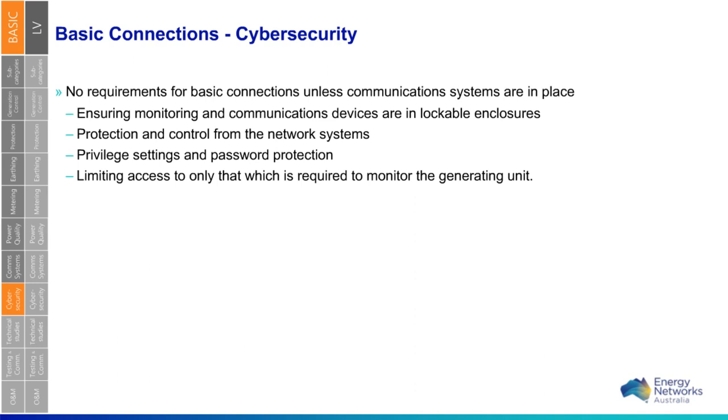So with cybersecurity, where there are no communication systems in place, there aren't any cybersecurity requirements. But where there are, we've set out some of those requirements there: ensuring that devices, monitoring and communication devices are in lockable enclosures, protection and control from network systems, so things like firewalls are in place, privilege settings and password protection, as well as making sure access is only to what's required to monitor the generating unit.